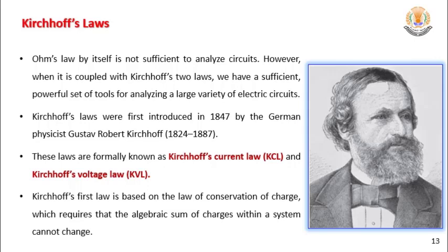What does it mean? You can consider the currents entering the node positive, and the others, in the opposite direction, leaving, will be negative. Or vice versa. It doesn't matter. If you consider the current leaving the node, like I1, I2, as positive, I have to write I1 plus I2, minus, opposite direction, I3, I4, I5 are entering the node, so these will be negative.